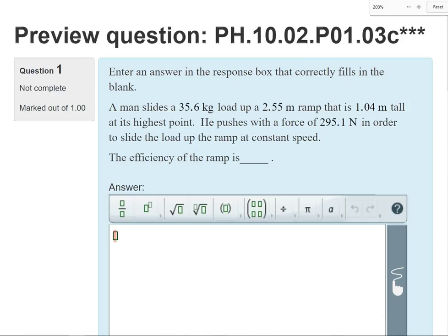Efficiency with conservative and efficiency without conservative force. Well, okay, but there's another simple way to calculate it. You can calculate it as the ratio of actual to theoretical mechanical advantage. That works. There's another ratio you could use. Get the same answer. Remember? Force used. Not force, work. Output work over input work, right? Output work is always going to be less than or equal to the input work. If it's less than, then that means the efficiency is less than 1.